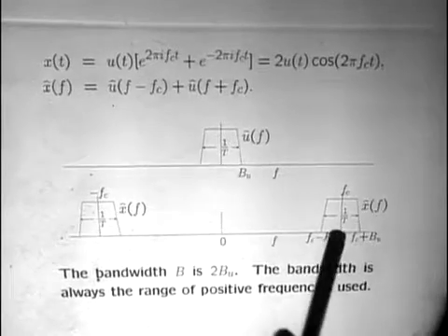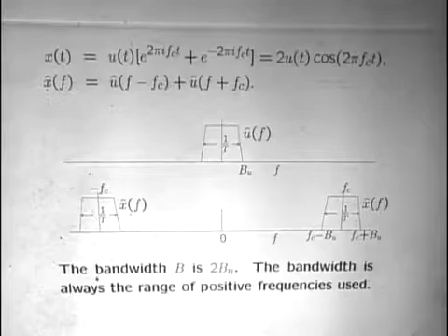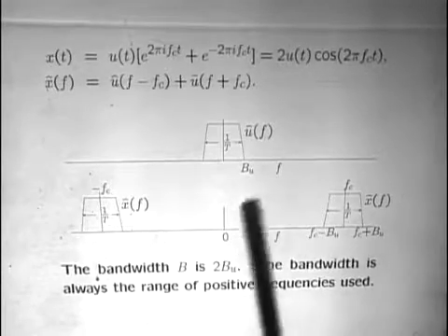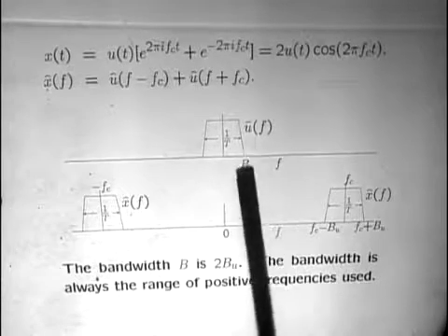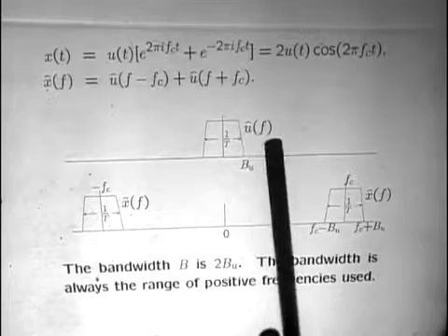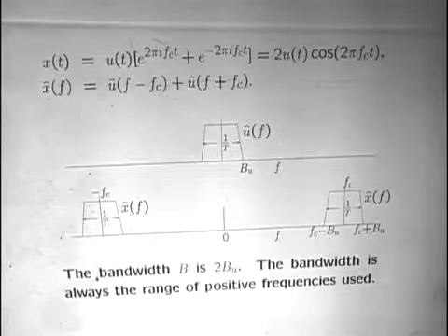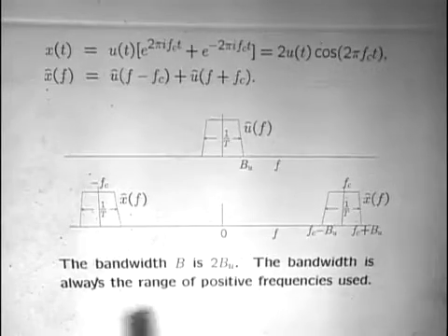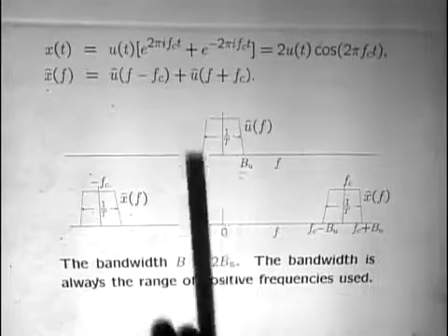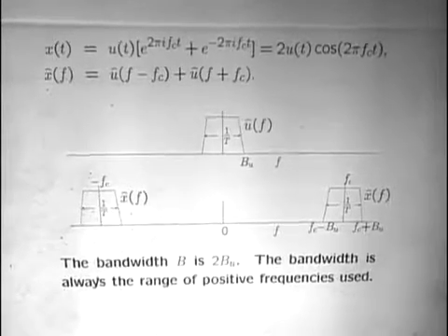Okay, so this gets shifted up. It also gets shifted down. And the transmitted waveform then exists in the band, which I'll call B_u. B_u is the bandwidth of u(t). Namely, it's this baseband bandwidth that we've been talking about. But unfortunately, when we do this, this thing shifted up and this thing shifted down, the overall bandwidth here is now twice as much as it was before.